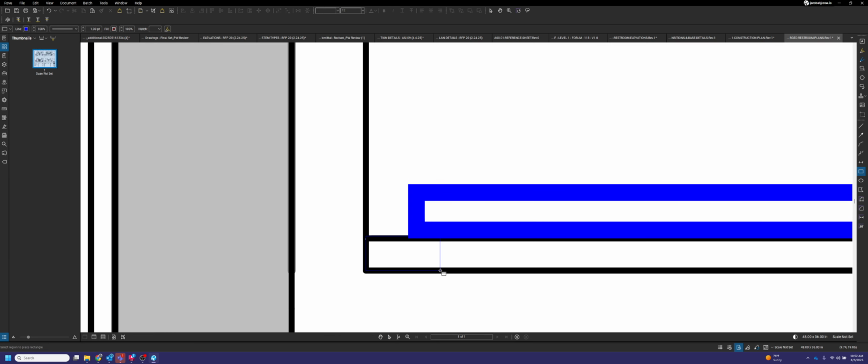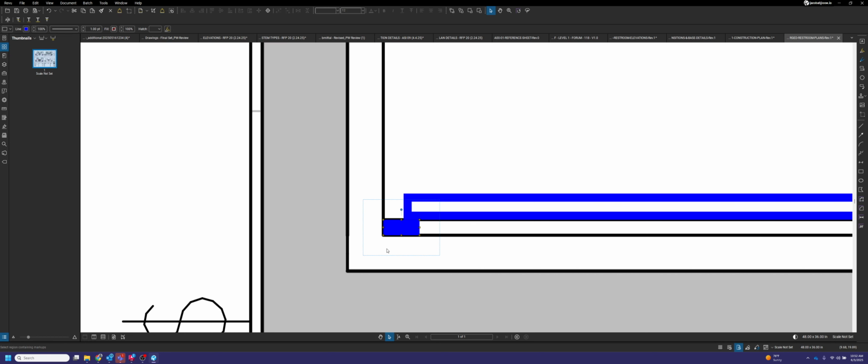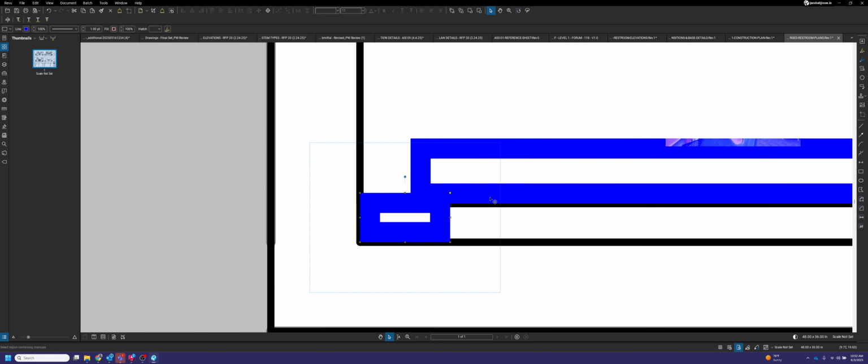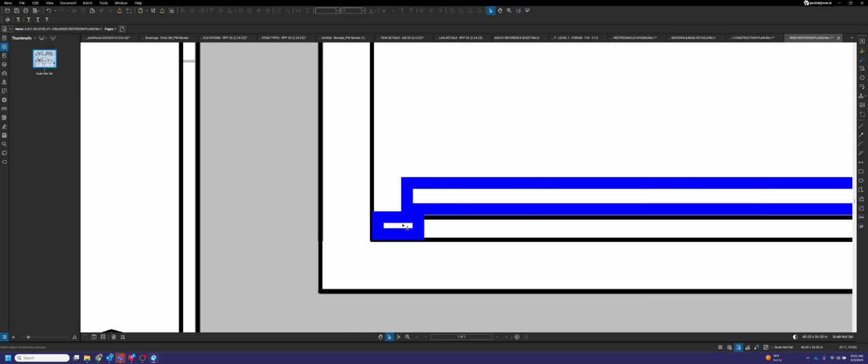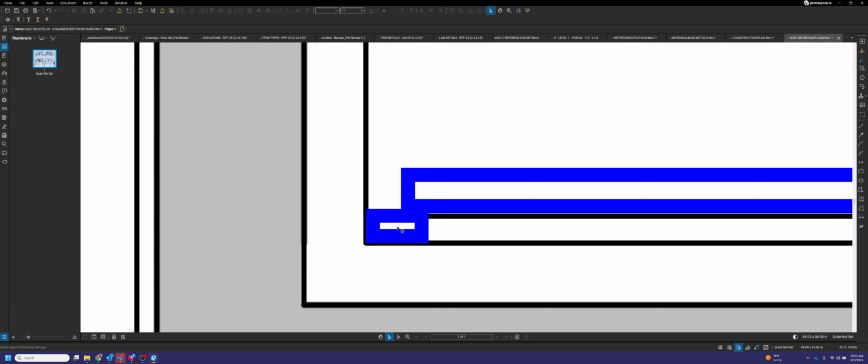But what that would look like is if this here is your wall, you would show your panel in this line here, this box here, and then you have your full depth reveal sitting between that panel and the wall. And that is going to typically be 3/4 inch wide at the front. So keep that in mind. Full depth reveals, we usually will go 3/4 wide. This block, typically what I'll do is I'll make that 1.5 inches. That way it is as wide as the reveal plus a little bit past the panel.